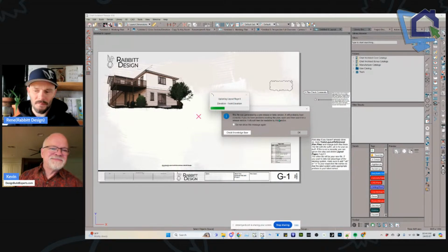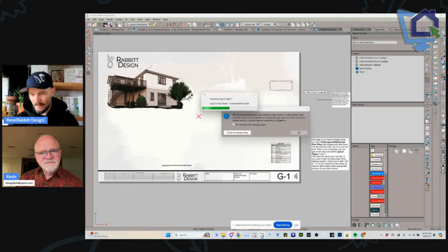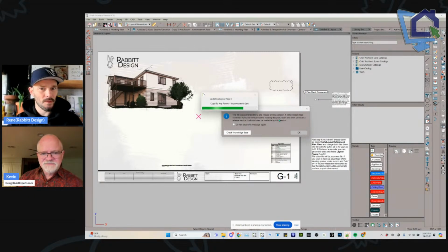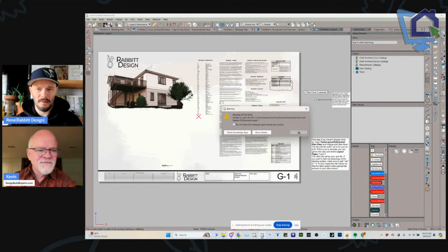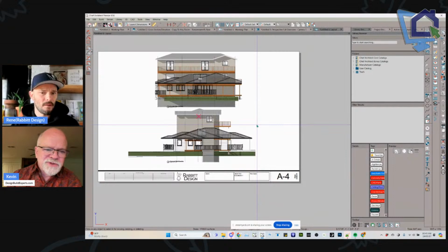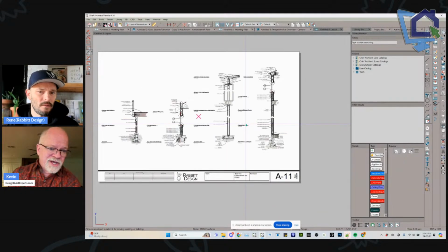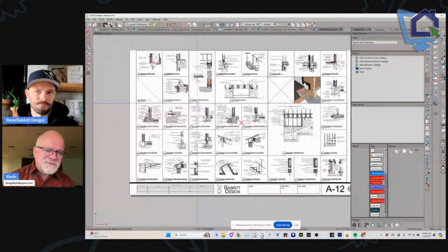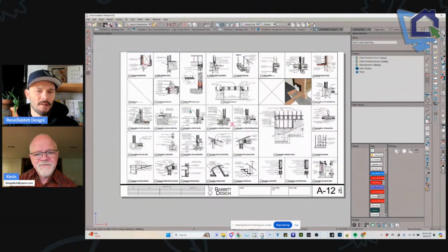The warehouse method, in case you've never set that up before, just means that we have a set of details and views and plans that are already established, and all we're doing is relinking to our current project, and those views populate and layout. I call a warehouse plan the one that has everything I can drag in from the sides and place in that particular page or drawing. So those are my warehouse plans. I'm going to open up the plan that this references, so we just have that to work with.